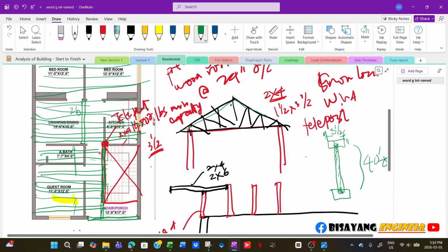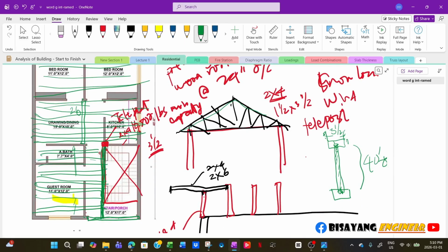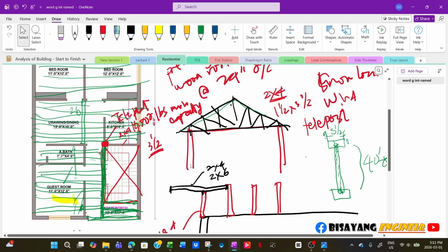And then this will be an opening, and this is a beam, this is a beam, and this is a beam also. The joist here could be a flush beam, then there will be a separate joist here, a really short span. Sometimes we specify only 2 by 8 or 2 by 10. But if you want the same ceiling height, so you don't have to provide shims, then even if it's overkill, we will specify the same joist here as on this area. So that's how it is framed.